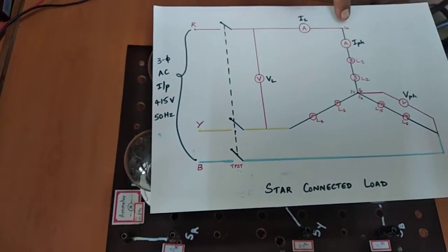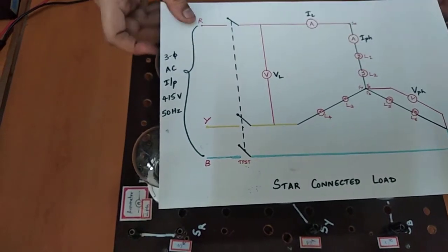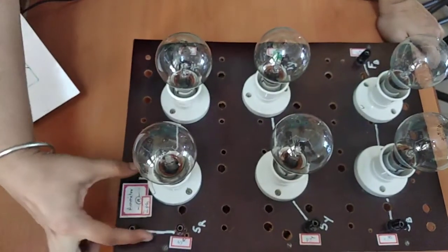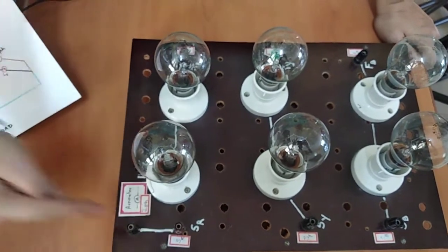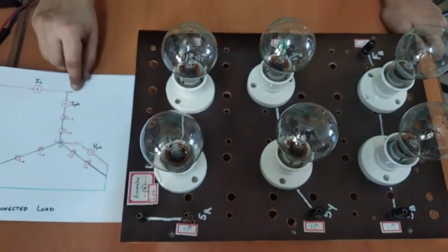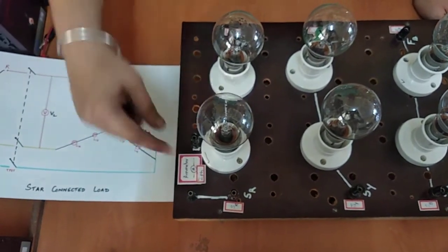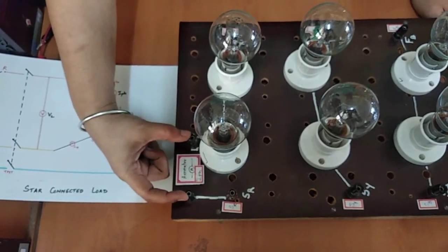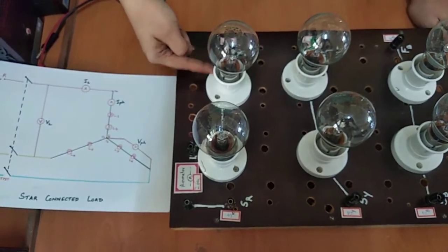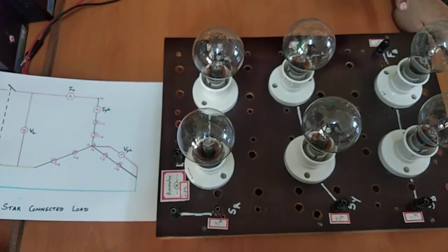So we know that after SR we have an ammeter here, right? So we also have the provision for ammeter connection here. So SR, ammeter, lamp 1, lamp 2. So SR, one terminal will be connected here. This is ammeter, and then lamp 1, lamp 2, and then finish. Similarly, this and this load.